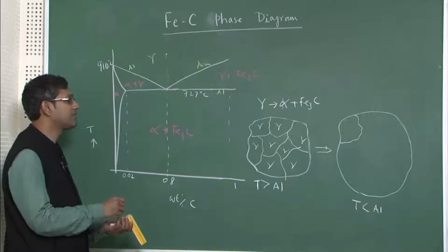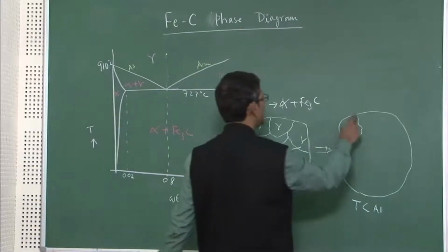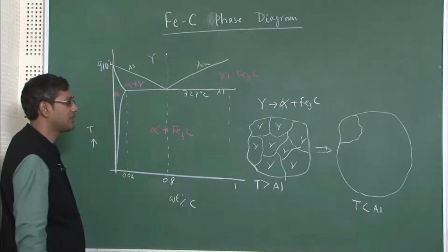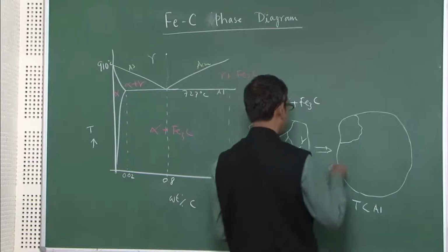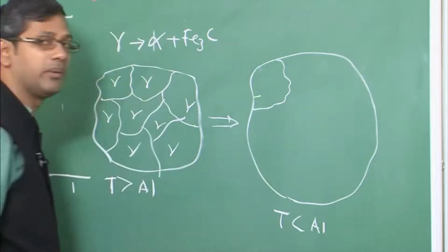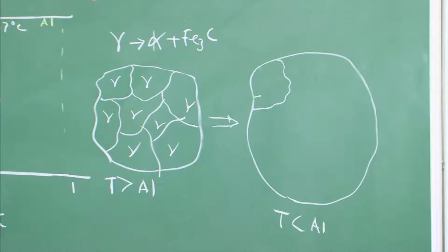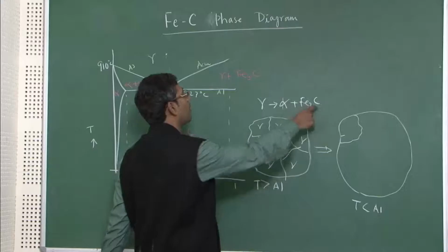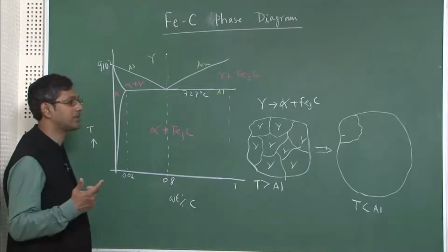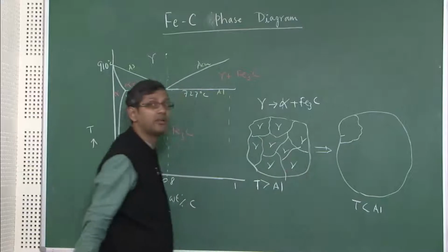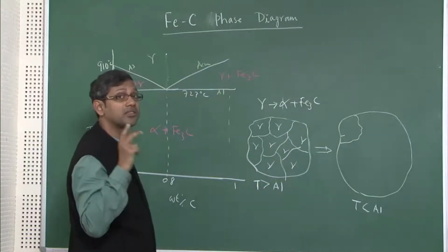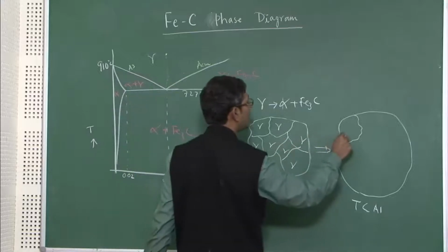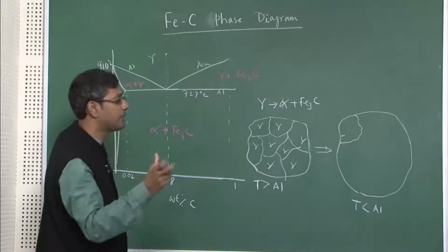Suppose this grain has a uniform carbon concentration of 0.8 weight percent. Now, by some means, which we will discuss later, suppose cementite nucleates in some part, and Fe3C will then grow. Basically, every phase transformation starts with nucleation. Cementite contains a huge amount of carbon, 6.67% carbon. Remember, each grain contains about 0.8% carbon, and to nucleate cementite I need 6.67 weight percent carbon, that is a lot of carbon. So it will draw all the carbon from the nearby region. Why?